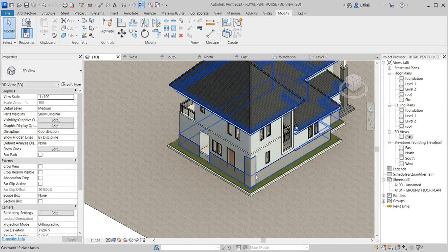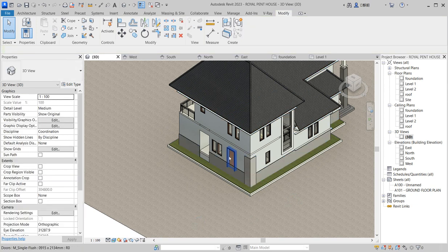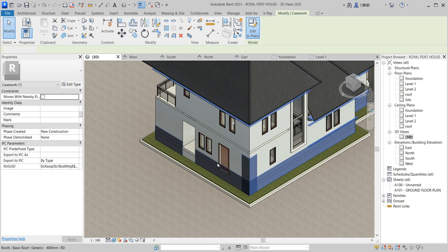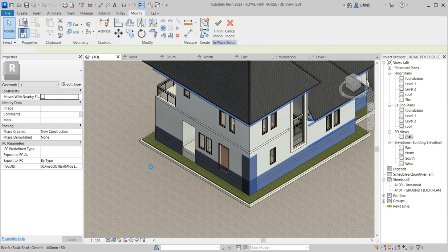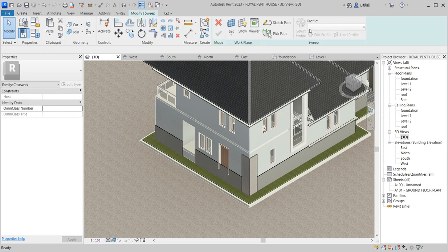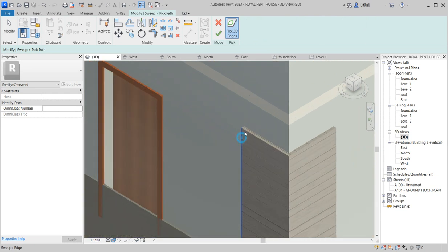So but later I'm going to work on that. So select this one now and say okay, there's a door here that I have issue with again, so I'm going to work on that as well. So what we do here is that say edit from here. You say create sweep, but now you use pick 3D so that you'll be able to do something wonderful for yourself.